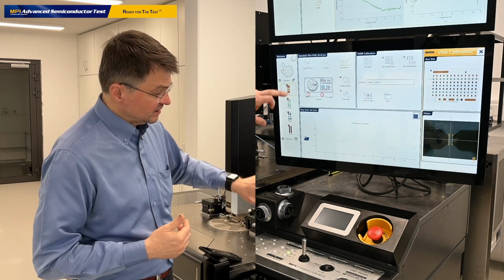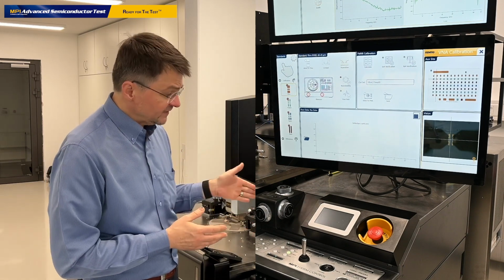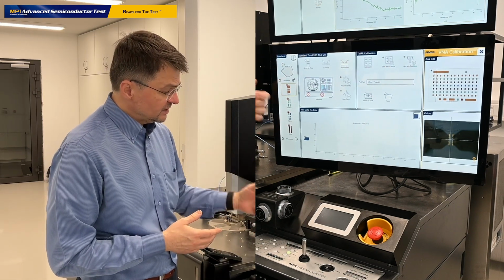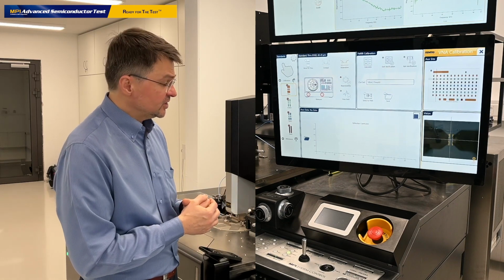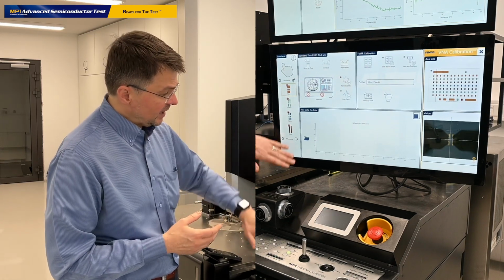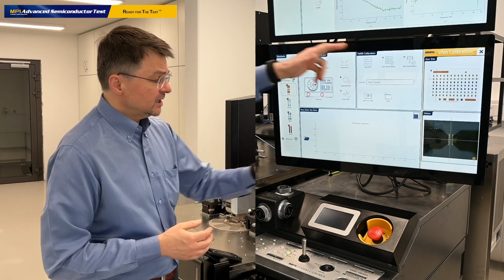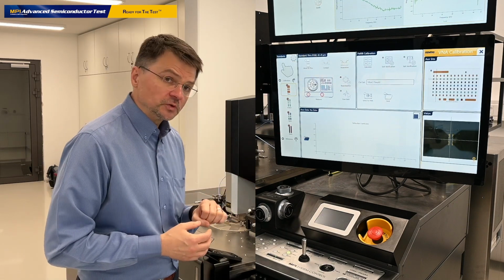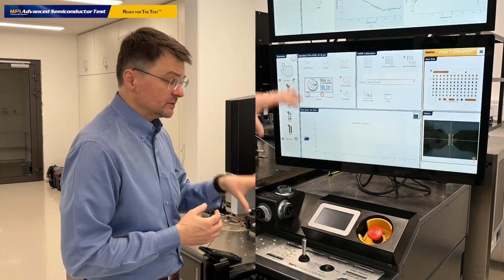We have the calibration standard list here on the left-hand side. This is the through, this is the load, this is the open, and this is the short calibration standard. And we execute it by the standard playlist. Then we have a widget that controls the network analyzer and it controls the probe system.